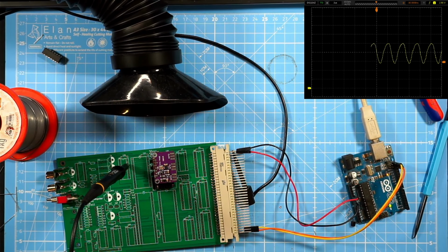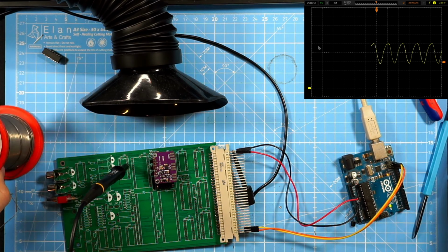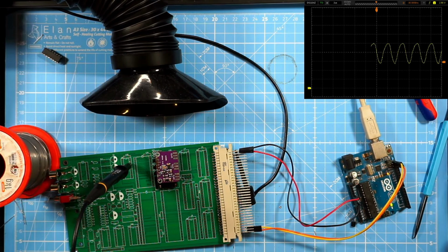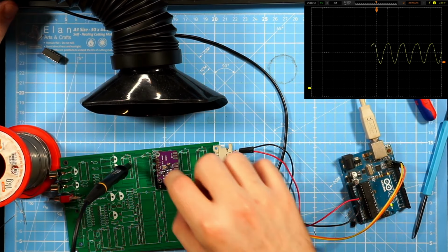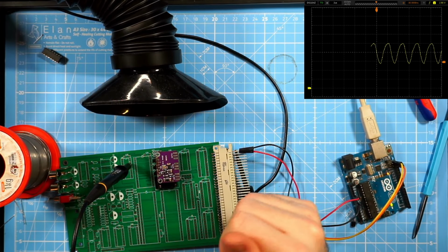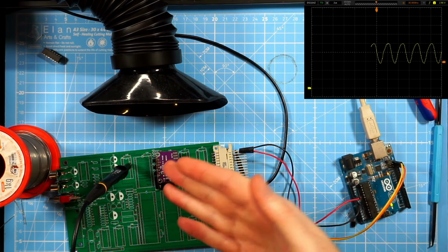Unfortunately you can't see it on screen, but on my scope itself, it says the minimum voltage is 1.2 volts and the maximum voltage is 3.37 volts. Let me just look it up. It's not what I wanted. I wanted 0 to 5 volts, but maybe it's not very much better than the clock chip itself. So if this is enough, maybe I could just bypass it, and this would also be enough. So this whole circuit would be unnecessary.